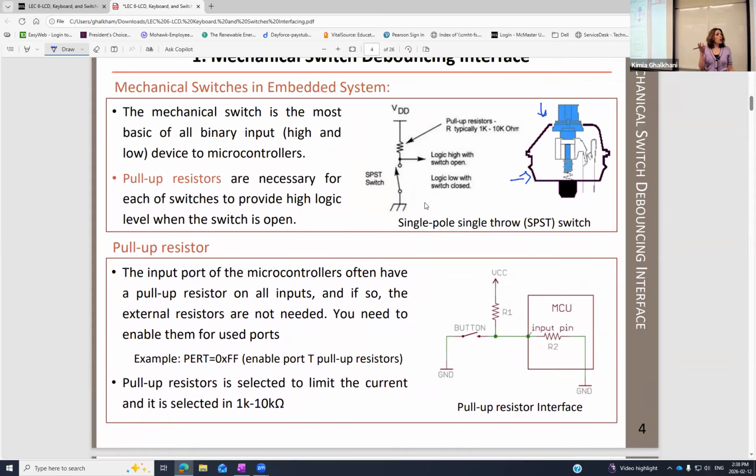Why do I call it single pole, single throw? Do we have any other type of switch? Definitely, yes. And what's the definition? Single pole, single throw means in this kind of switch, I'm going to have only the switch connected to one input, and of course, be able to communicate only to one output. There are situations where we do have more poles and more throws. You may even see it right now in here in the room if you check on the walls, or you may see it in other applications. So we have double pole, double throw, and so on.